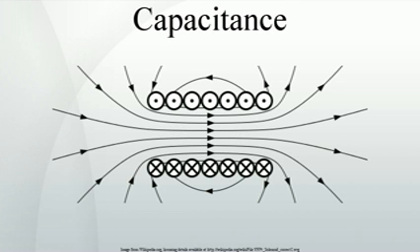This field polarizes the dielectric, which polarization, in the case of a ferroelectric, is a nonlinear S-shaped function of field, which, in the case of a large area parallel plate device, translates into a capacitance that is a nonlinear function of the voltage causing the field. Corresponding to the voltage-dependent capacitance, to charge the capacitor to voltage V an integral relation is found, which agrees with Q equals CV only when C is voltage independent.